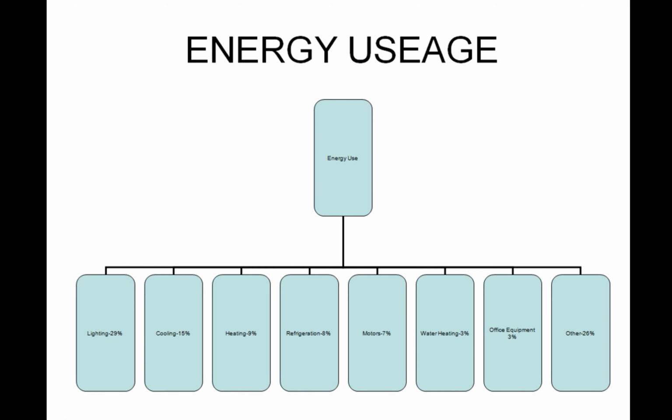The typical is that it's about 30% lighting, 15% of the usage on a yearly basis is cooling, 9% is heating. All right, we talked about cooling having a little more energy consumption than the heating abilities. And of course each of those are used throughout the year, so combined really heating and cooling is about equal to the lighting, which is year round also.